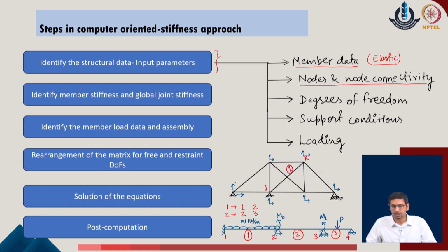As we go to trusses, the similar idea also needs to be reflected. We define the respective joints on the given problem, and corresponding to it, I need to define for each of the members. So, if I say that this is some member number i, I have to say that corresponding to member i, the connecting nodes of the given problem are 2 and 6. So, this is one piece of information which one needs to provide.